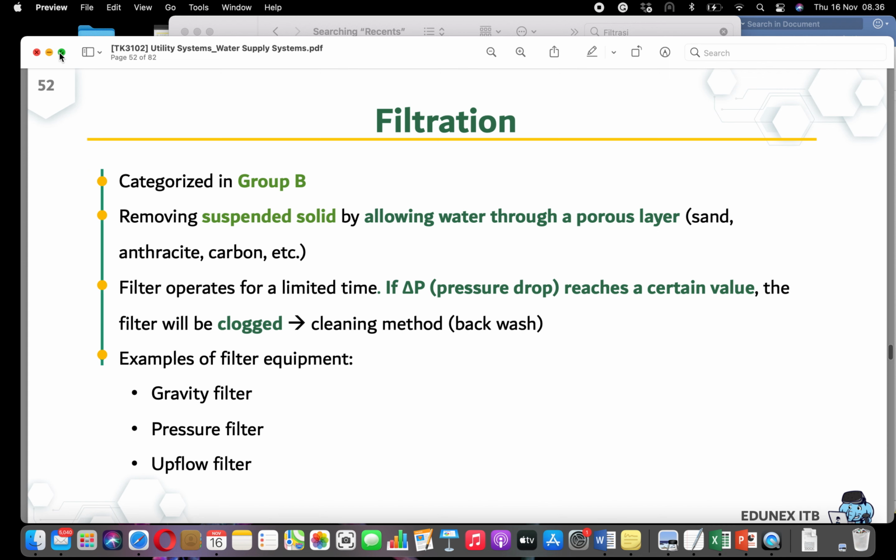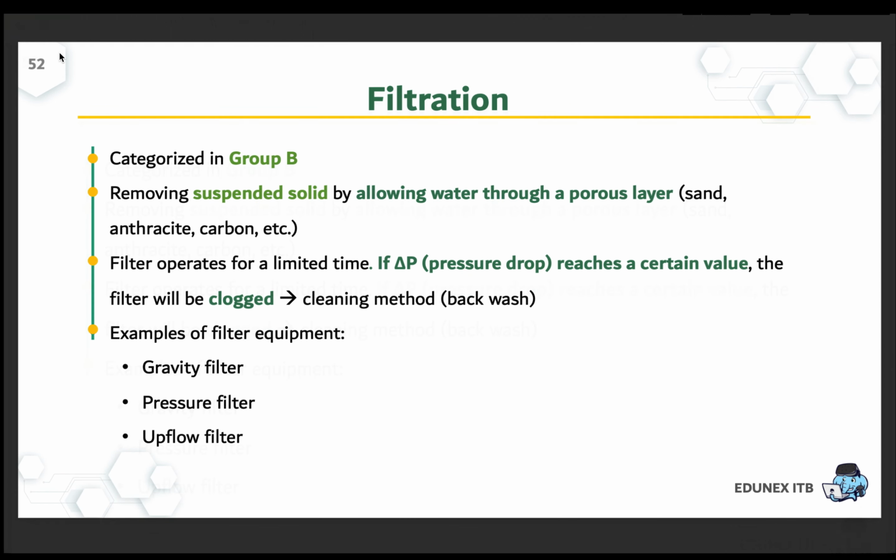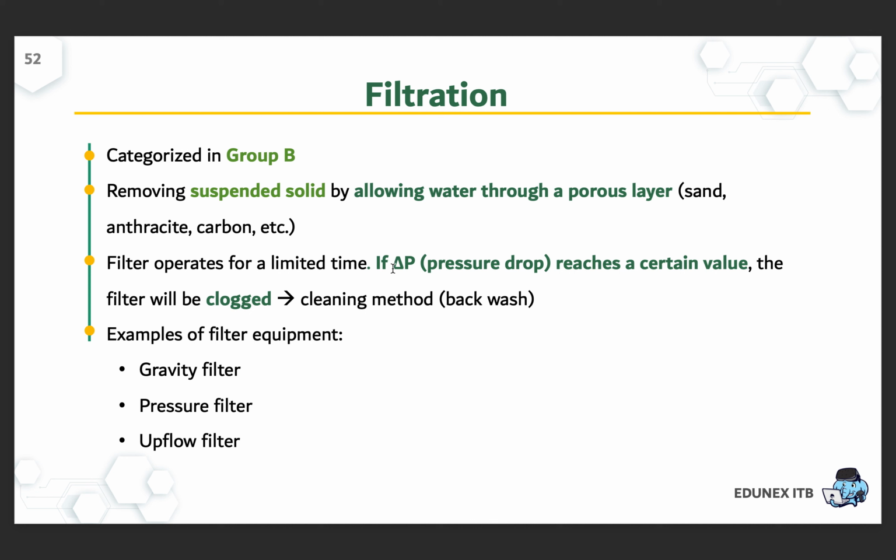In our original slides, this is stated that the pressure drop is the driving force, and if the pressure drop reaches a certain value, the filter will be clogged or can be categorized as clogged. You don't need to wait until the filter is completely clogged. You don't need to wait until you have no filtrate at all to stop the filtration and clean the clog.